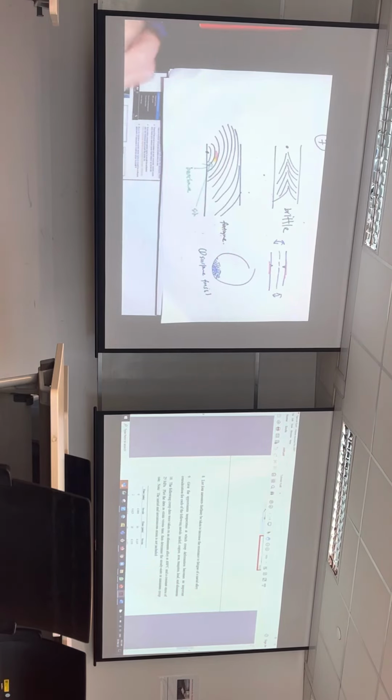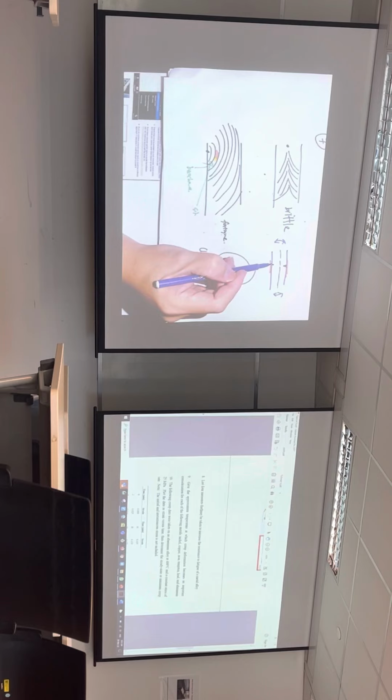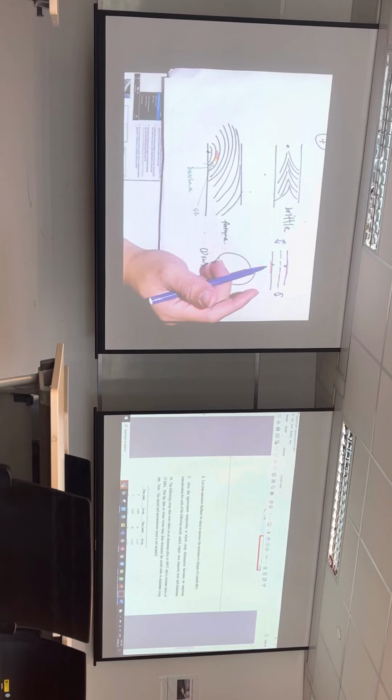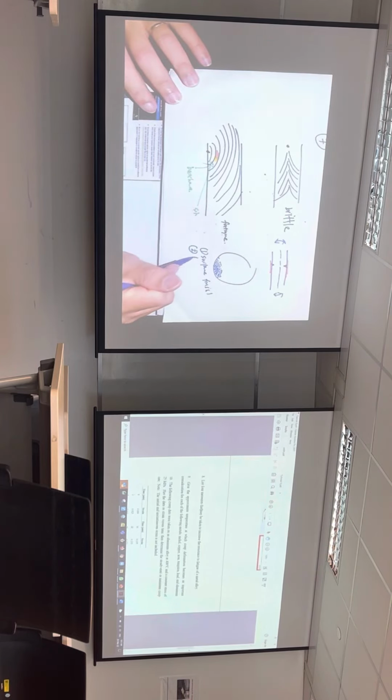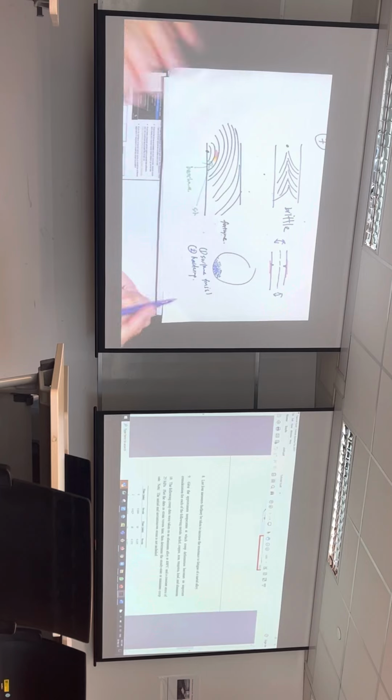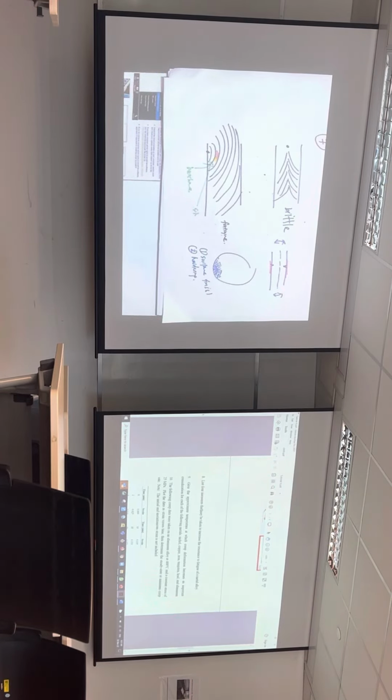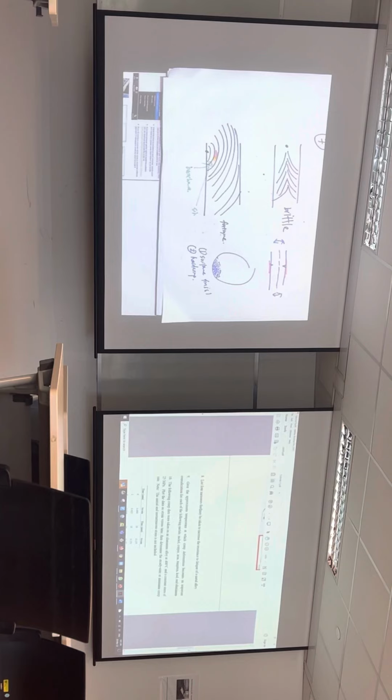The other thing you can do is prevent scratches, because a crack can be initiated during applications. If initially you have a very smooth surface finish, but later somebody scratches it, then you also have a crack initiation. So you want to prevent the scratch, and to prevent the scratch you can do hardening. You can do hardening by, for example, shot peening, by shooting particles to cause plastic deformation. So the outside becomes harder, and it's far more difficult to scratch later.